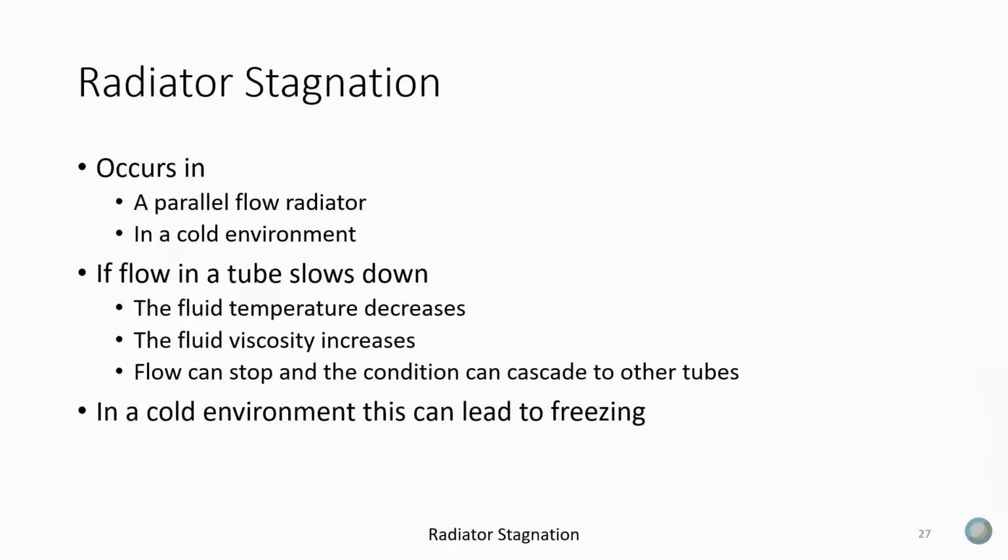It might be worth pausing here for a moment just to note that, as I said, Apollo used a stagnation radiator. And that was a decision that was made fairly early on because they were working with differences in environments going from low Earth orbit out to the deep space environment as you're heading out towards the moon. And although they kept the sun on the side of the spacecraft and had a rotation of the spacecraft around its central axis of a rev every 3 minutes, I believe, there were still times, long periods of time, where the radiators were looking at deep space.